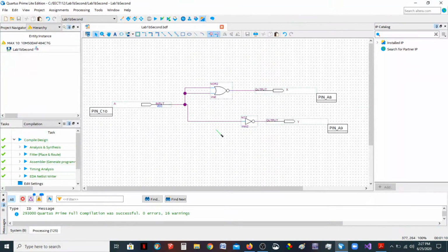So I come back to here, and I want to point something out, okay? If I were to do something like this and ask you to have both inputs be connected to one single input, that means there's only two combinations, right? Because if A is 0, then what's on the input is 0, 0. If A is 1, then what's on the input is 1, 1. So there's only two possible outcomes of this NOR gate, right? So think yourself through that. What happens if you have 0, 0 on the input of a NOR gate?